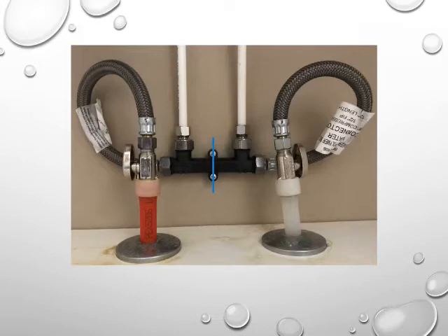But the key here is that we don't have to let the hot water side run until the water gets hot. Like I said, I had mine set up for 15 minutes out of every hour. You might find that you want it more often than that, or don't need it that often. But it certainly saves water. It's a nice water saving piece. And this is what they call a cold water return. It uses the cold water return.